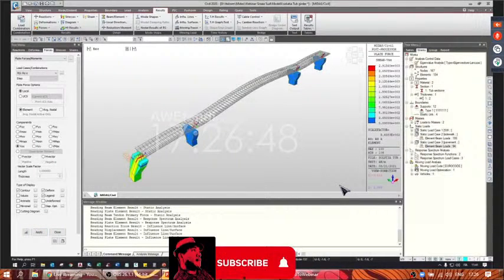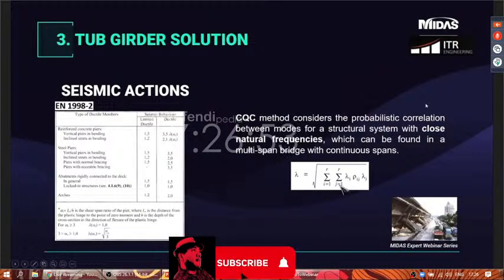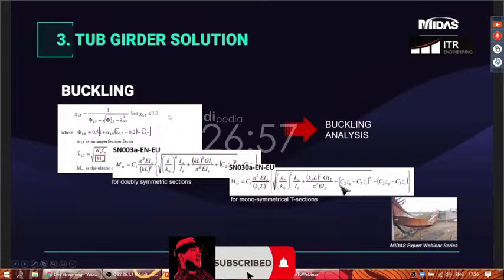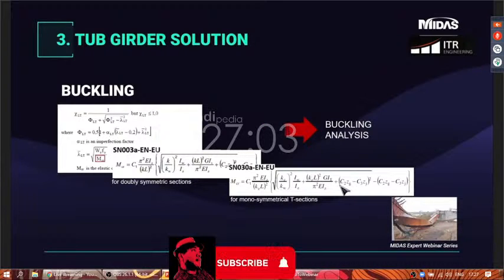Now we go back to the presentation because we are going to talk about buckling. Lateral torsional buckling is a serious topic for metallic structures, but in composite sections, generally, the slab connected to the steel partially mitigates the problem, acting as a constraint for the section which is not free to deform laterally.